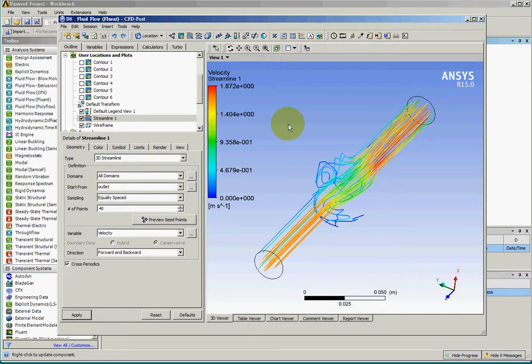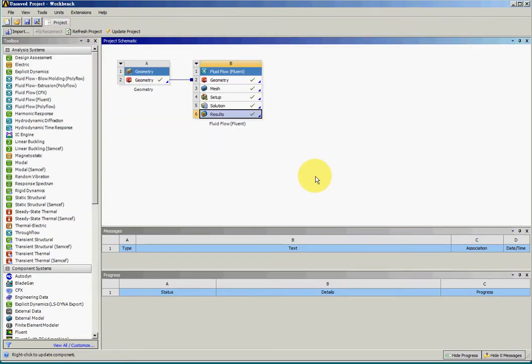The most important thing that I want to talk about here is that you can understand the procedure of a Fluent flow simulation in a 6-step model. The first step is drawing a geometry in a CAD system, and the second step will be meshing. Actually, this is the first step also, the meshing and defining inlet and outlet. And then enter Fluent. And in Fluent, there will be 6 steps.